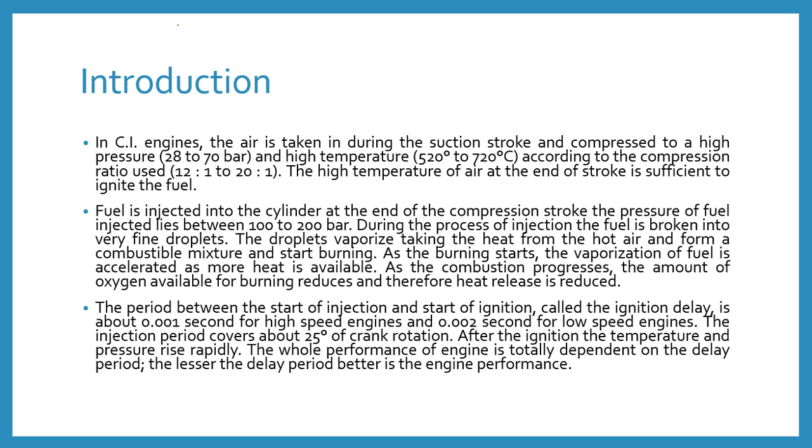The high temperature of the air at the end of the stroke is just sufficient to ignite the fuel. Fuel is injected into the cylinder at the end of the compression stroke. The pressure of the fuel injected lies between 100 and 200 bar.